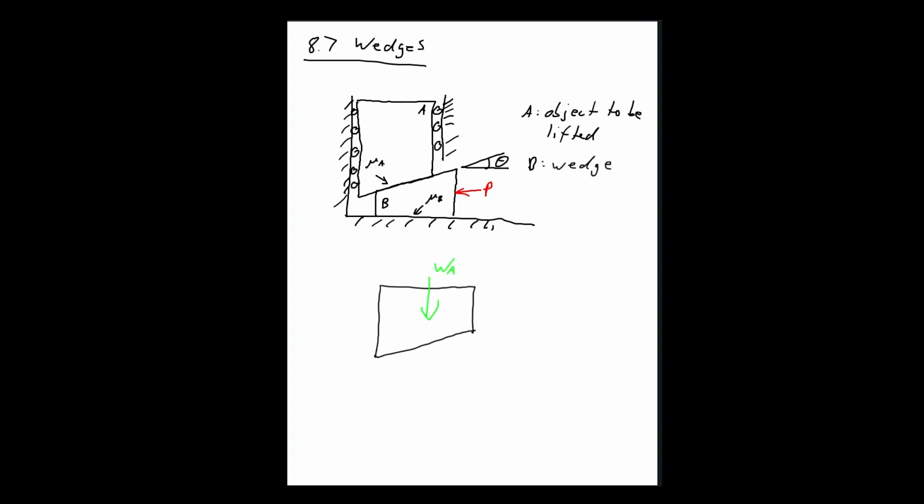Remember that whenever we take away a roller, we replace it by a normal force. Now if we're pushing the block to the left like we have right now, then we're going to push against these rollers and we're going to pull away from these rollers. So it means the rollers on the right will not have a force because, as you remember, the roller only takes up a force towards the surface, not away from it. So all that we have on normal forces up here is N_A.